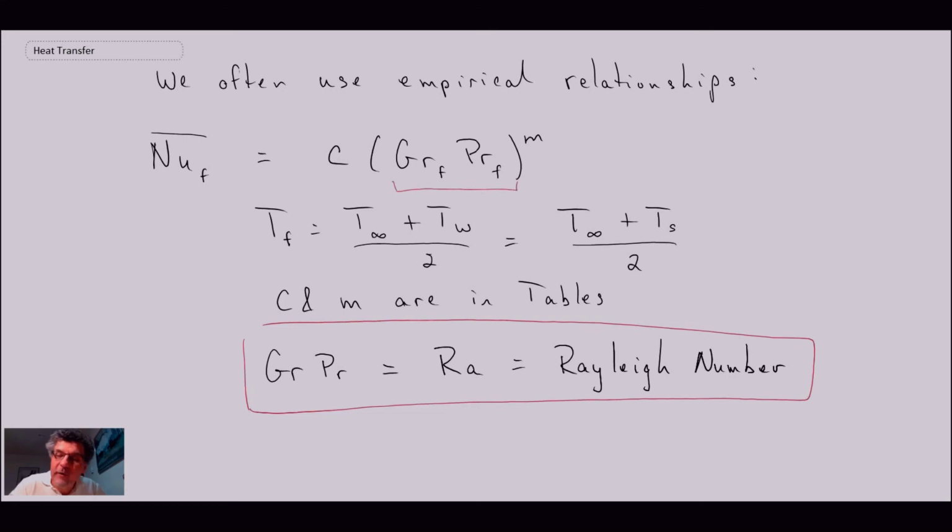So that's a bit of an order of magnitude analysis between free convection, forced convection, and combined free and forced convection. And it turns out that it is quite often difficult just to have pure free convection because you do often have mechanical forcing, people walking by, there might be ventilation in a room or something like that. And so it can be challenging just to have natural or free convection. You usually are in this combined mode. But anyways, what we've seen here is the way to be able to figure out orders of magnitude, and when either the free convection or forced convection would be applying.